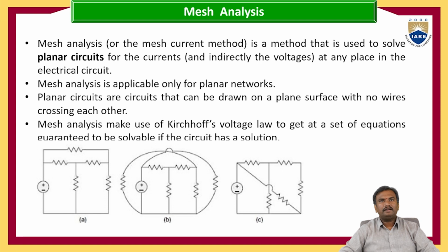Here, mesh analysis is the method that is used to solve planar circuits for calculating the currents at any place in the electrical circuit, and it uses Kirchhoff's voltage law. By using Kirchhoff's voltage law, we are going to calculate the currents. And mesh analysis is applicable only for planar networks, where planar circuits can be drawn on a plane surface with no wires crossing each other.